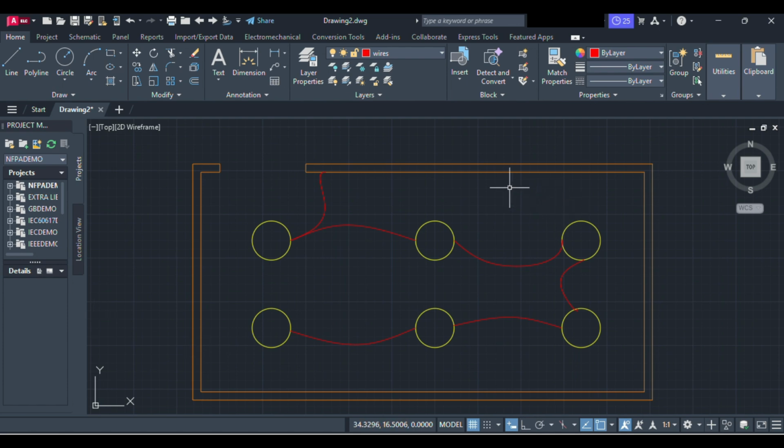This comes in handy. They look more aesthetic than those boring straight lines, and arcs are pretty hard to draw, and SPL makes the job easy and faster. Now to modify it, you can simply select it, and in this drop down you can modify it using this point, or you can click here and control the vertices like this, and you can also edit the lines like this or like this using these vertices.